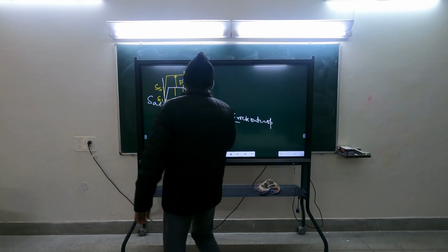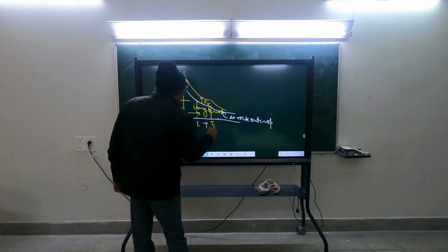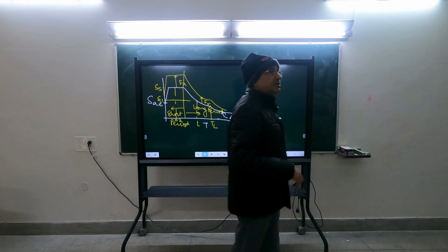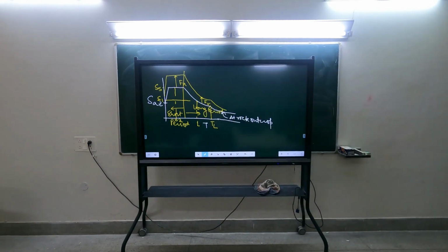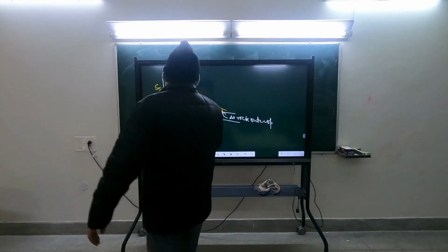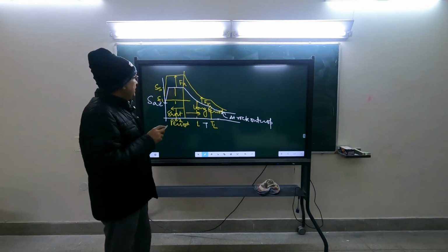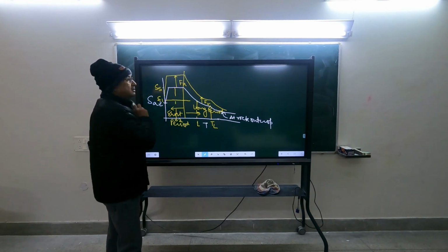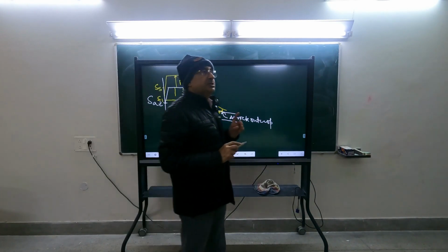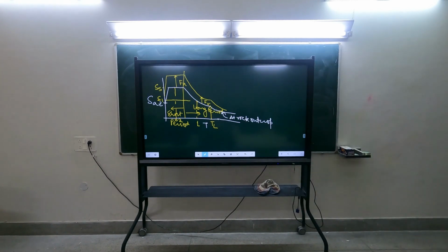You need only one more point here, from where the displacement control range starts. So they provide contours. If you look at ASCE 7-2016, they provide contours for SS, contours for S1, but with different return periods, and TL for the whole country. So these three parameters are required to define this response spectrum fully. What approach is our code having? It gives you the shape and just the value at 0 period. You multiply that shape by the 0 period value, and you will get it.